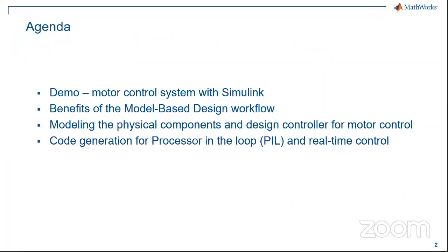So here's today's agenda. First of all, I will show you a demo for a motor control system with Simulink. Then I will talk about why and how model-based design can help and accelerate your workflow. And next, I will dive into how to build a motor control system from scratch by using Simulink and Simscape, including how do we parameterize the motors and design the control system by generating pulse width modulation waveform, PWM, for inverter drives.